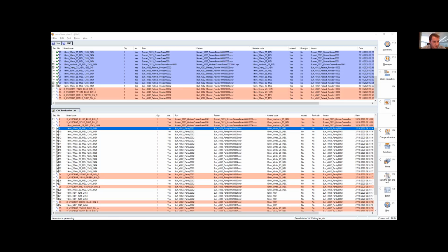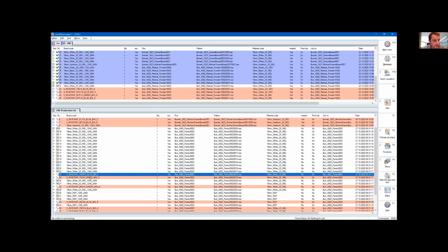For sure. All I'd say, just to make it quick, would be what we're having in the output file from Microvellum. It'd be different if we were using Cut-Right, but we use Microvellum for our optimization. Are you seeing my screen still? We do. Whenever there's a scrap pattern in the optimization, I could pull it up, but most of you probably know what it looks like. In your optimization, when there's a scrap pattern that you're going to use, the PTX populates with that scrap code. X is what the software recognizes as offcut, and MV scrap is our signal to our operator: okay, this is a piece of scrap that I'm pulling from our rack.